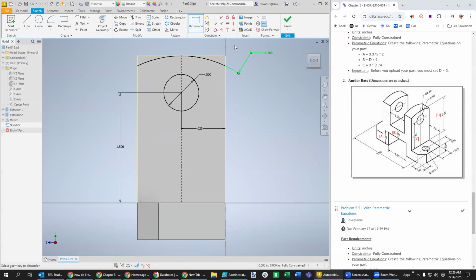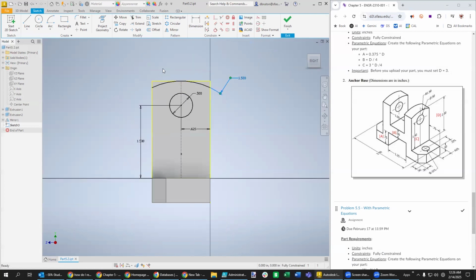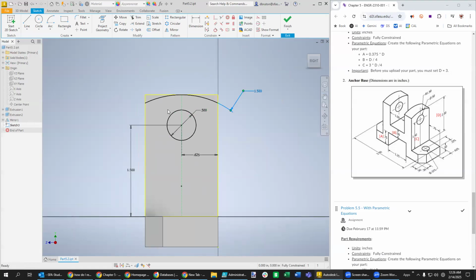like so. And just to show you, that's not really part of the radius. That's just part of the dimension. We could pull it over there for a moment. And we do need to make this a cut that comes through there. So let's make this cut bigger than it needs to be because there can be some unusual things happening here if you have like a 0 dimension cut. In other words, if I just made this shape like this, that line would go right through that point. So what I like to do on these is to make my cut too big, just cut through air, so to speak, like that, and then see if that helps.